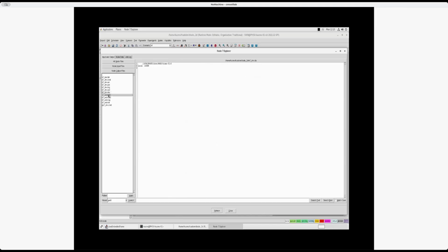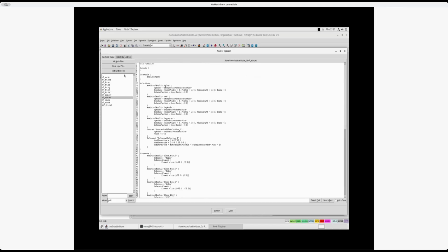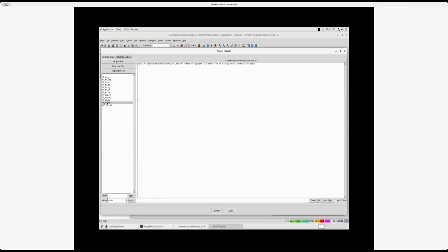You know, submission data, local submission error script. In that case, this is another common file being generated, so it has its own log. And the final result, it's usually these TDR files. So these are the files that along all the simulation are going to be representing your devices. And so these are plottable, and we can look at them.